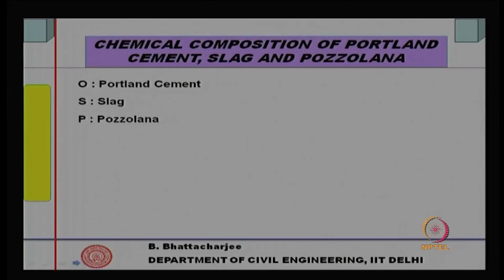When Portland pozzolana cement is produced with fly ash, what is done is you take the Portland cement clinker, one of the popular routes, there are other routes also, and grind the fly ash together with the gypsum to get what is called Portland pozzolana cement. By proper grinding and adding additives, you can actually compensate for somewhat slow strength development in case of pozzolana. Pozzolana strength development is relatively slow for two reasons. One, the reaction itself is relatively slow.